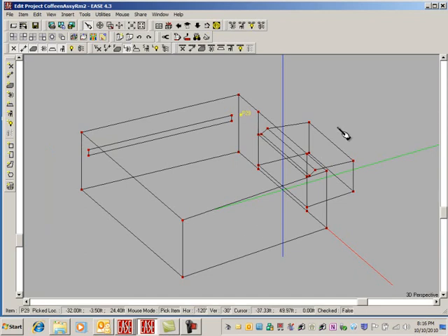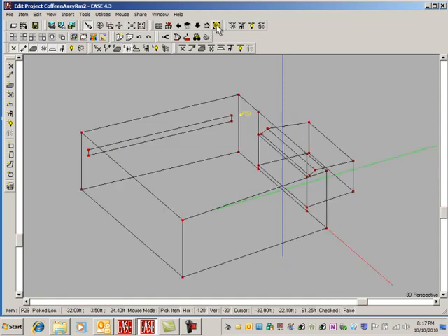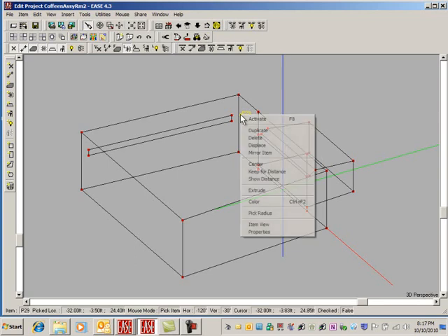So then we could establish the one on the other side. The symmetry is off now, so we have two choices. We could take this vertex and duplicate it over here 64 feet in the plus x direction, or we could mirror it around the x equals 0 point. Either one would work. Well, we haven't tried mirroring anything, so let's just mirror it, and it's going to be mirrored symmetrically across the x equals 0 point. So we just say OK, and we should have established another vertex.